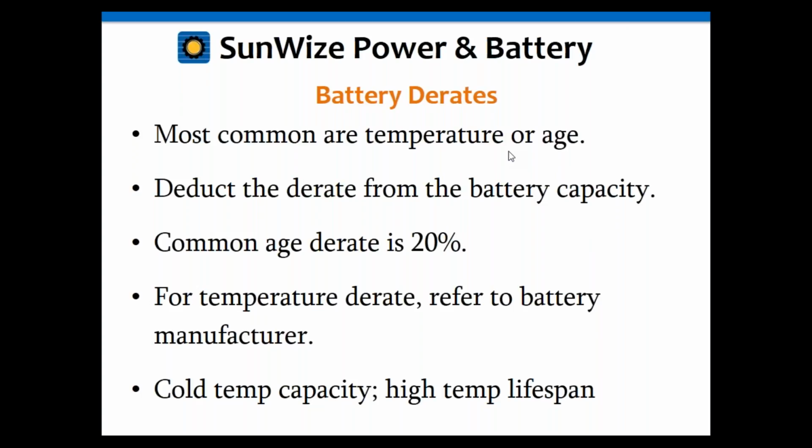And again, what's going to happen is that batteries are rated at 77 degrees Fahrenheit, 25 degrees C. Anything above that, the capacity is about the same. They go up slightly. It's below that where it starts to degrade, especially once you get around freezing and colder. They can drop off quite a bit, actually. I think the curve just gets a little steeper at that point.